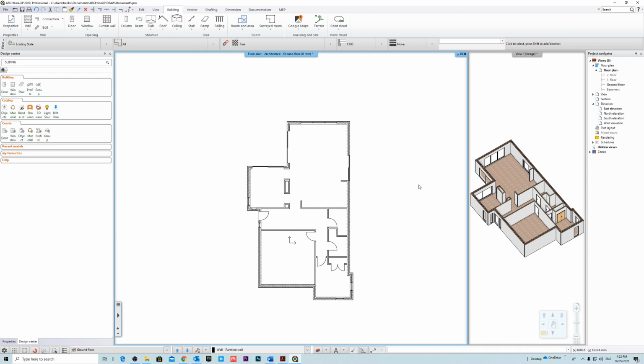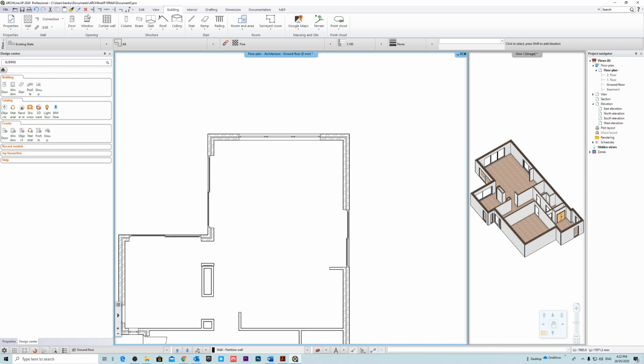Now the last thing I want to create is a foundation wall. Okay, so we're going to do that. I'm going to go to the foundation tool. I'm going to create a 300 by 300 foundation. So with slabs, you just need to go here to closed foundation.